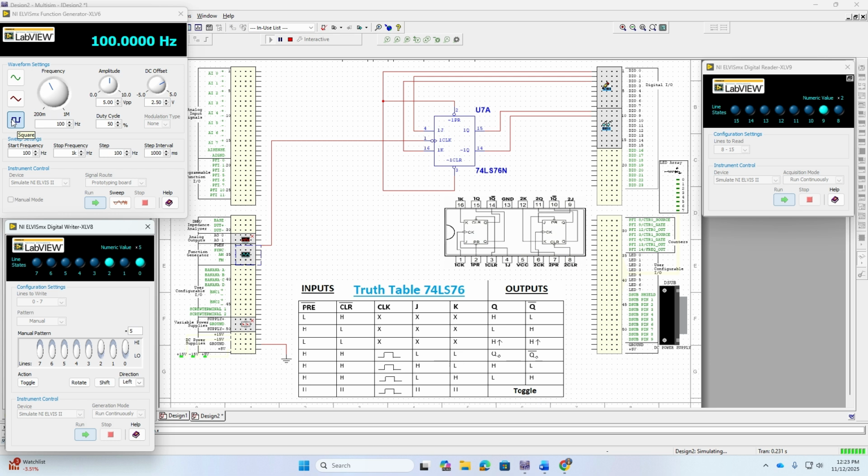What this means is, if I have 5 volts peak to peak, it's going to go 2.5 up and 2.5 down to give me a full 5-volt peak to peak as it oscillates above the zero baseline. But if I offset it by 2.5 volts, the baseline is at zero. Basically, I shifted the waveform up, so now I have zero all the way up to 5 volts, back down to 0 volts, and that's all I've done. That's what it wants you to do for the setup of the function generator. Just leave it like that.